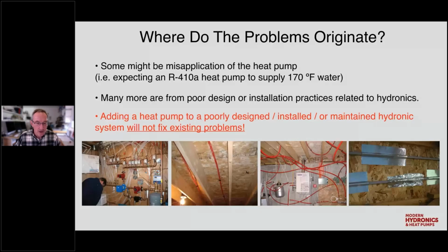We've got tubing just clipped to the bottom of the subfloor, and aluminum foil being used in place of aluminum heat transfer plates. These are just poorly conceived systems. And again, most of you would understand this, that just dropping a heat pump in isn't going to fix the existing baggage, I'll call it, in these systems.